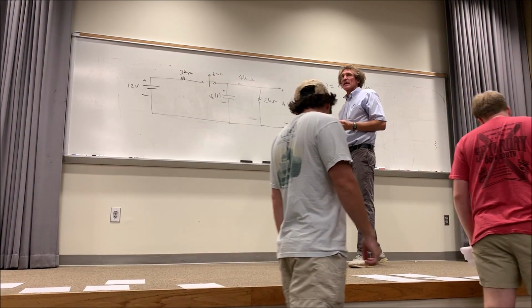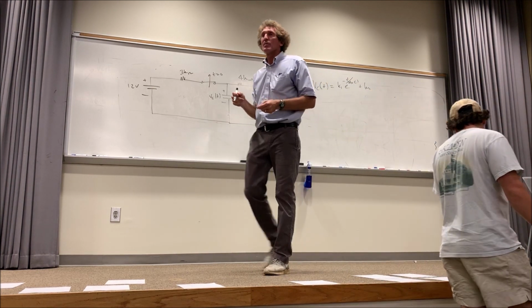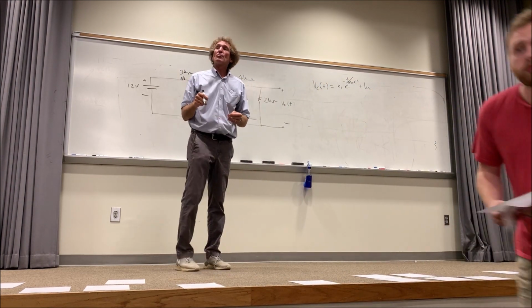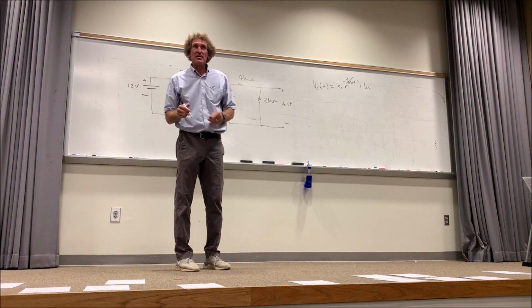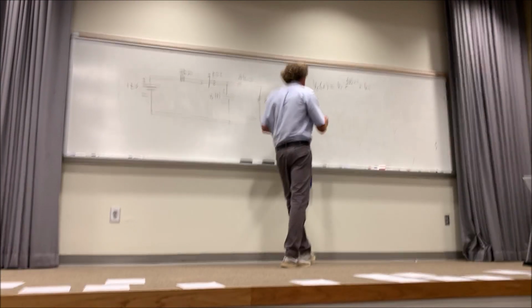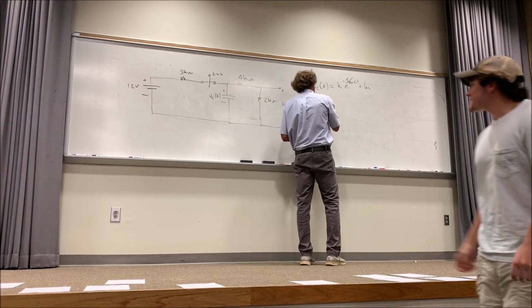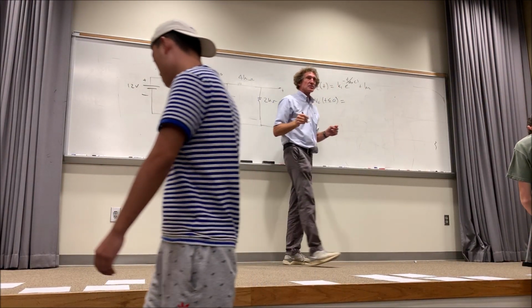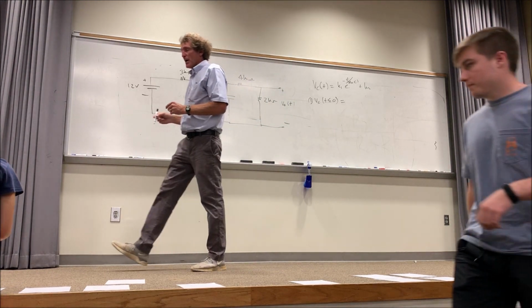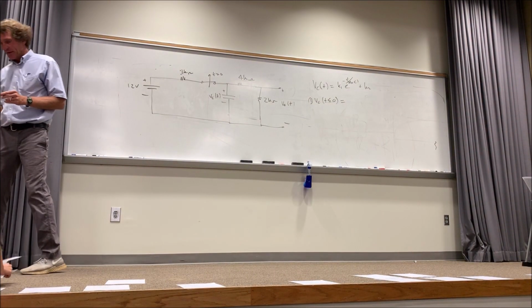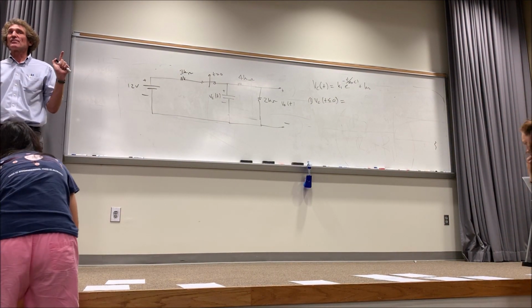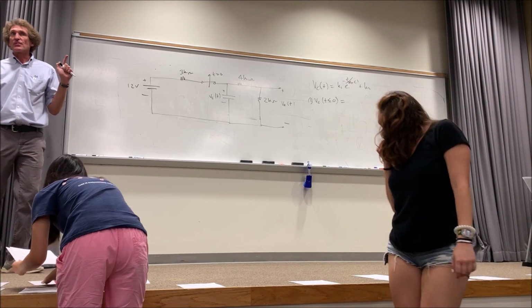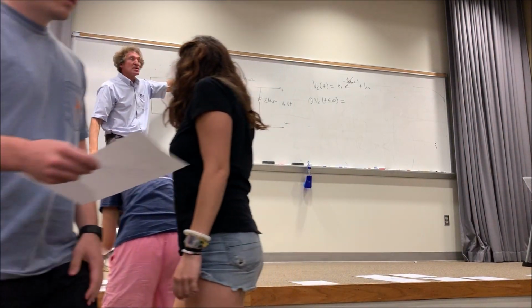Now, the steps I gave you really don't matter in the order, but I'm going to do them in the order I've shown you. First, you find the voltage at t equals 0. So the first step, VC at t less than or equal to 0, because that's where the switch changes. I want you to watch this carefully. Now, for t less than 0, that switch has been closed forever.